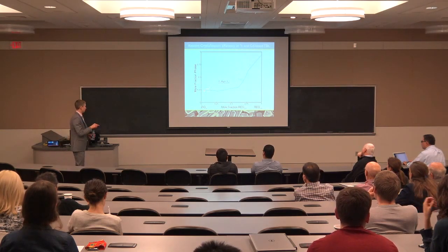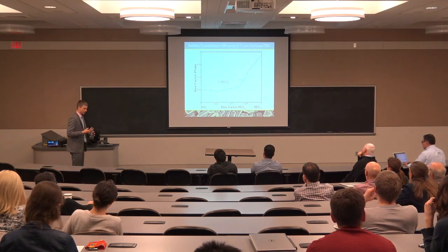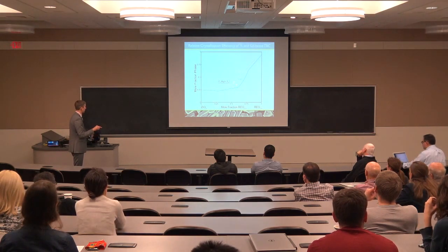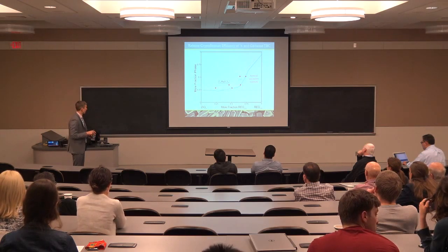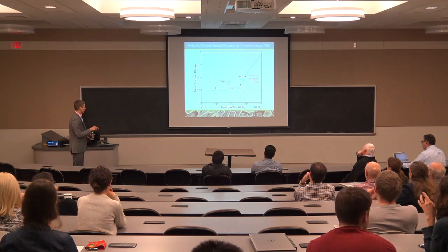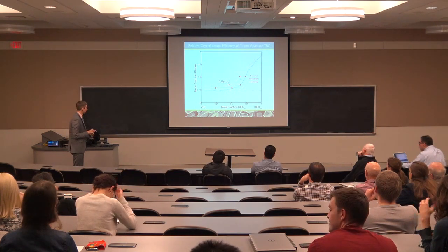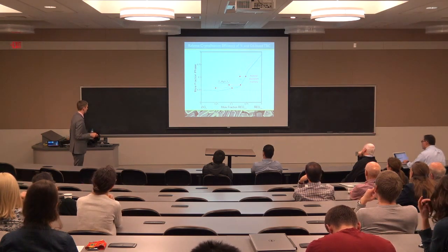And so if we pull these kinds of transition curves, which show the amount of crystalline material for a given coating composition, we see that the gadolinium is always higher. But from a design perspective, this is the comparison we need to make. If we have a gadolinium-based coating and we want to switch to an yttria-based coating, at what point do we get an equivalent amount of crystallization for the same amount of dissolved material?